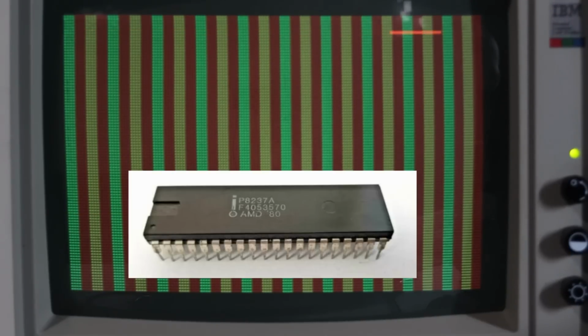Well, the CPU is reading its instructions from memory and then executing them, but unfortunately it's being interfered with because there's something else that uses the bus which the CPU needs to access memory, and that's the DMA controller. So the DMA controller is actually used for DRAM refresh on the PC.